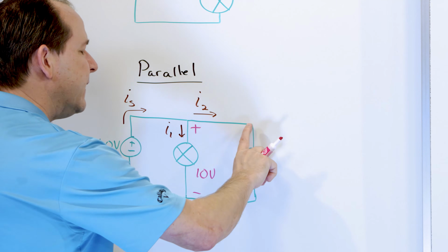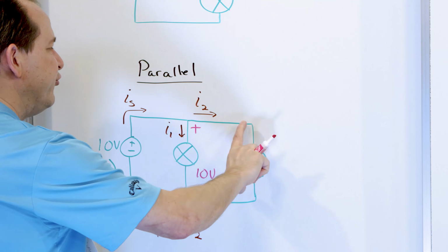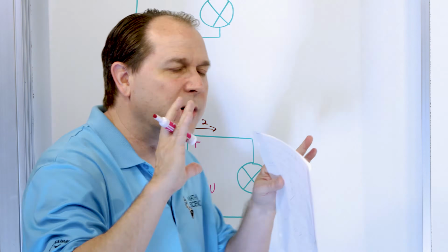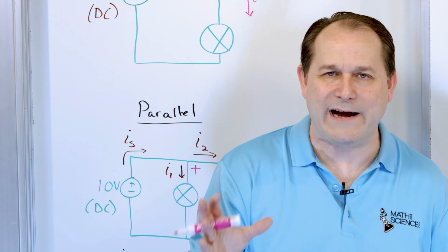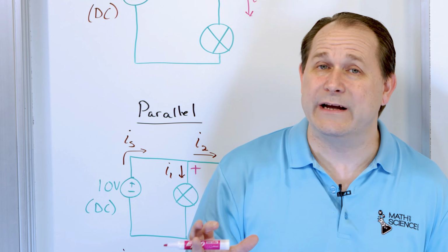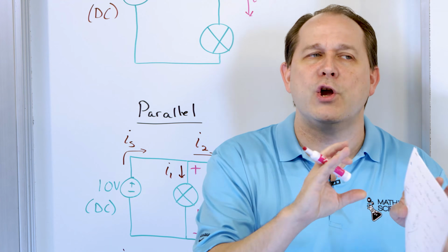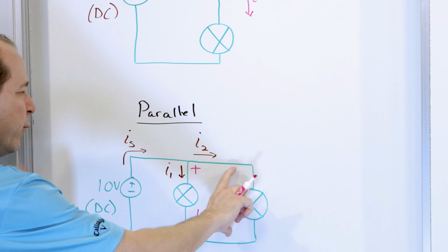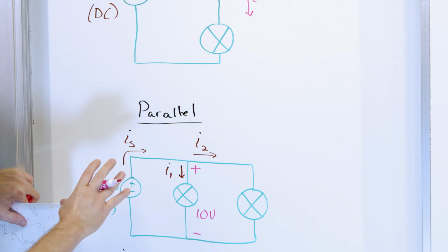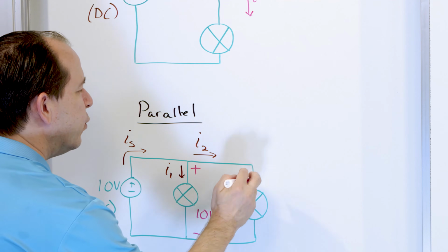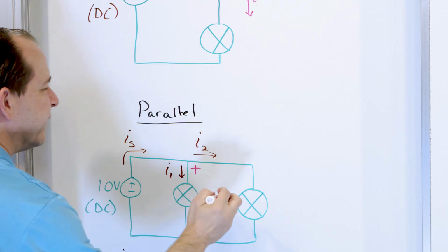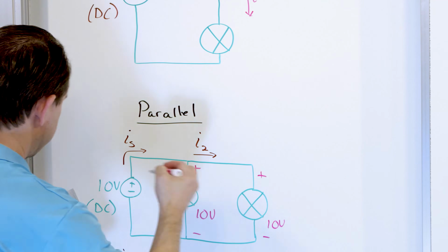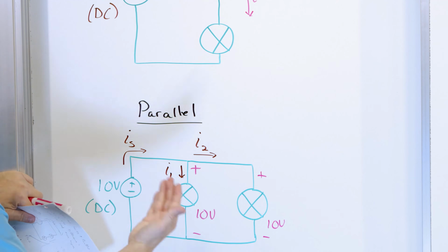And because this light bulb is also connected directly to here, which is also connected directly to here, and remember, we're assuming perfect wires with no loss in any of the wires, like perfection. We don't have actual wires that behave like this, but these wires don't have any influence or losses at all. Then we say, because this is connected directly to the source, that this also has a voltage drop of 10 volts, right? So that's another way of looking at it.